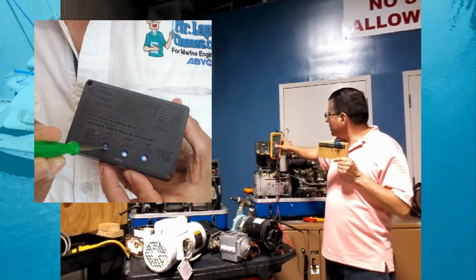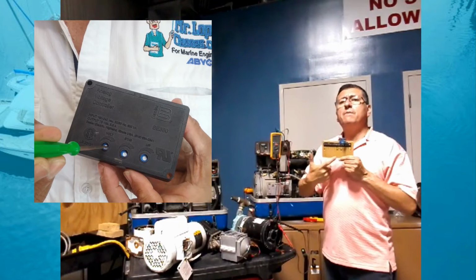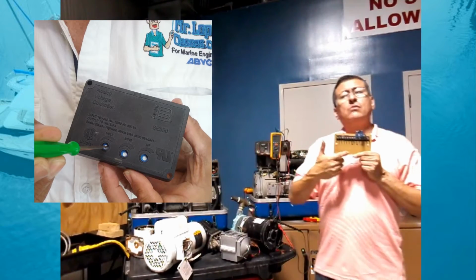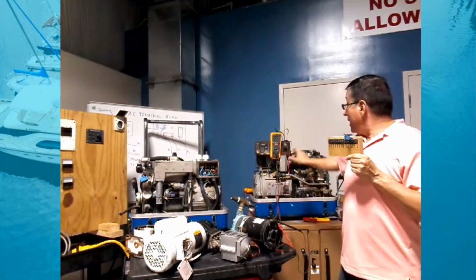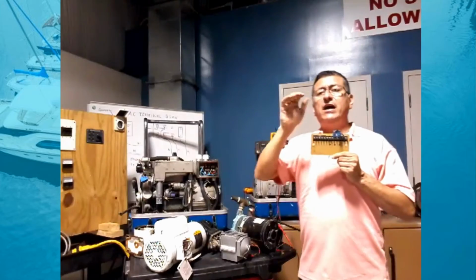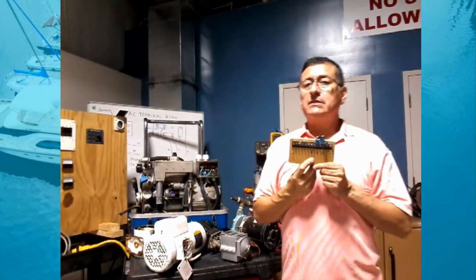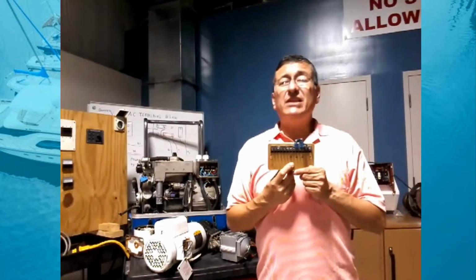And I check the voltage: 126, 124, 120, perfect. Now, with the voltage at 120, I turn on the breaker again, apply loads, and verify that the voltage stays at 120. The second spot is basically stabilization.